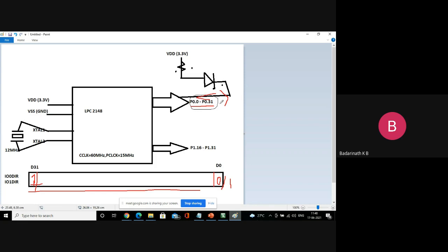That means that my logic, my program works. Most of the time, projects will not work. Your programs will not work in the lab when we give you a hardware board. What was the mistake? Usually, as I observed, most of the students fail in the exam. They will not get the result only because they have not configured the direction register.